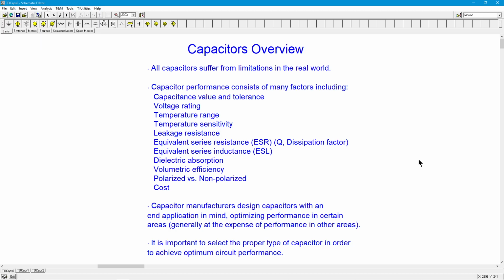Similar to this, we have something called leakage resistance. If you took a cap and you charged it up and you just put it on a shelf somewhere where nothing can touch it, and you come back to it sometime later, and that might be days or weeks, that charge will have leaked off. And we can model that as a parallel resistance, right? A leakage resistance. There's also a series resistance, something called an ESR, an equivalent series resistance.